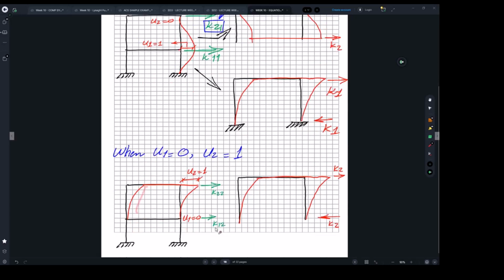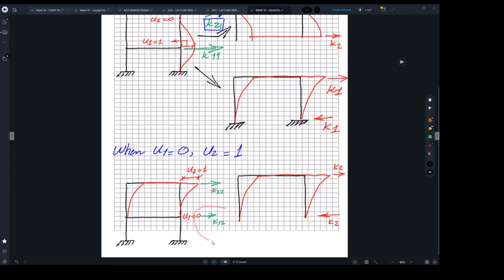And as I said, what you're going to do, you're going to put those green arrows, which represents the correct coding for the elastic stiffnesses. Here we're using 1, 2. As we said, the first number represents the influence happening at that floor. The second number represents where the displacement was applied. So 2 here is at the second floor, that's why it's 2.